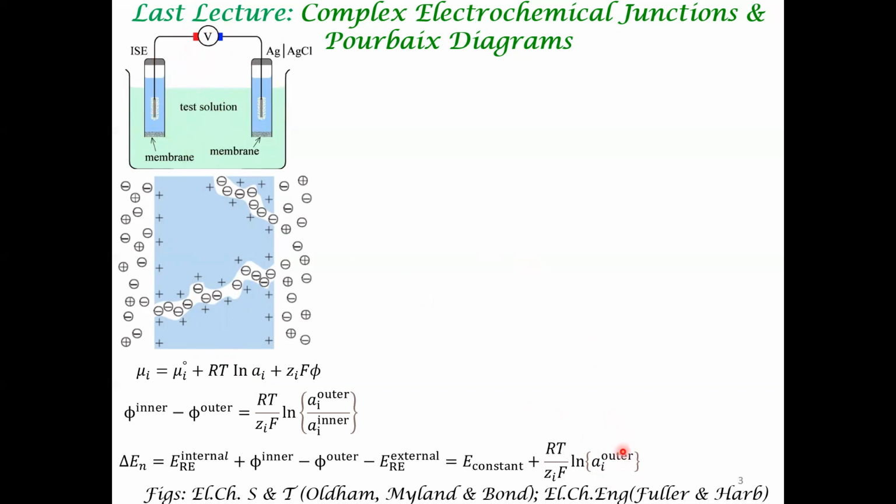So if you can develop a correlation, a calibration chart wherein different electrical potentials are calibrated to different concentrations of the test solution, you can use this ion selective electrode to detect an arbitrary concentration. What is very important to notice is that the electrical response can be correlated to the concentration of the ions in the test solution.